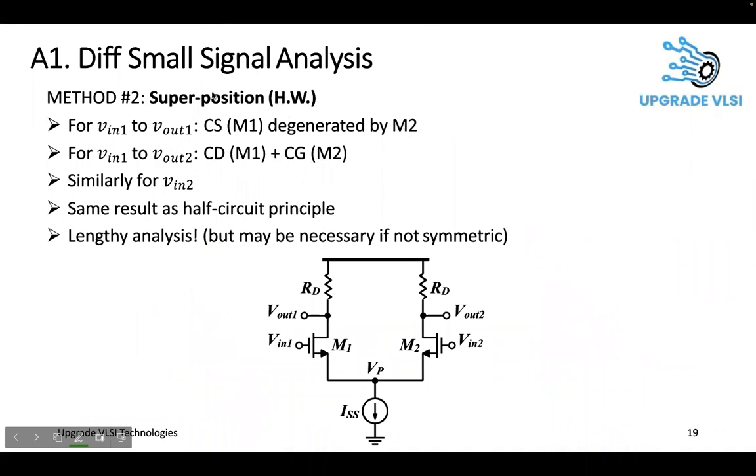Coming to the common mode gain, this is something you can do as homework. You can use the superposition theorem. We did RD divided by the resistance as the common mode gain, but we approximated it actually. This is RD divided by RS dash. That is the one we did. But if you look at the resistance here, it will be 1 by GM. So actually it is RD divided by 1 by GM plus RS dash. So this 1 by GM factor is still here.